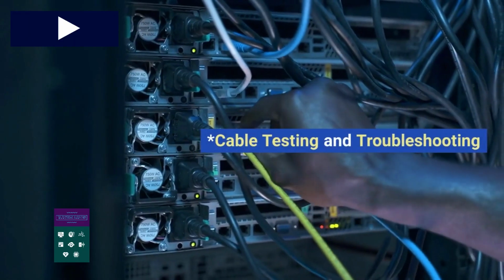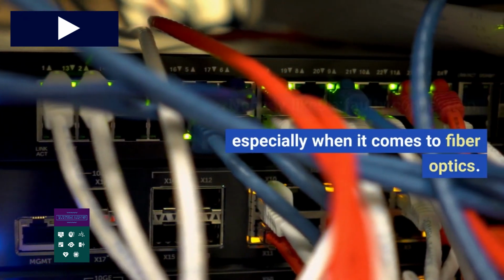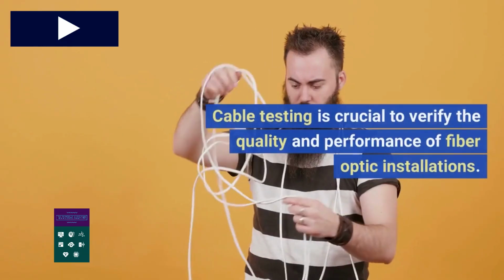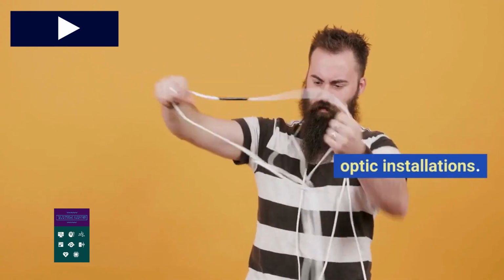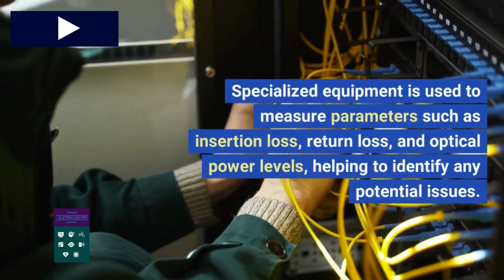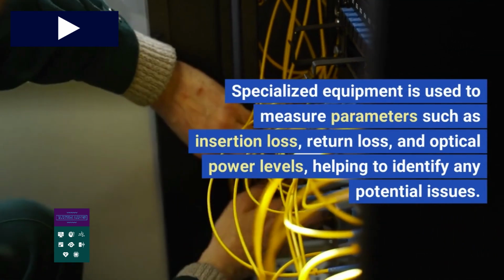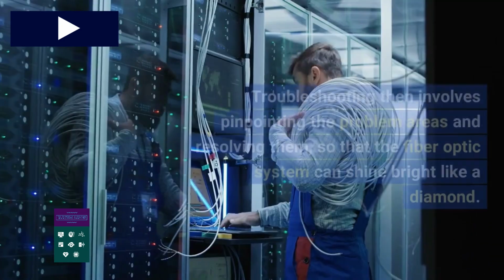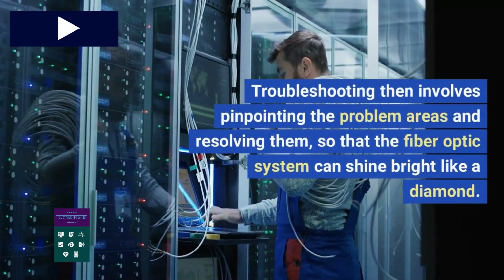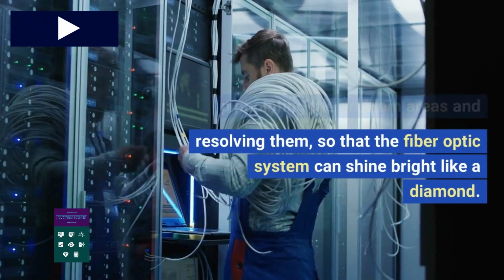Cable testing and troubleshooting. Nobody likes a faulty connection, especially when it comes to fiber optics. Cable testing is crucial to verify the quality and performance of fiber optic installations. Specialized equipment is used to measure parameters such as insertion loss, return loss, and optical power levels, helping to identify any potential issues. Troubleshooting then involves pinpointing the problem areas and resolving them, so that the fiber optic system can shine bright like a diamond.